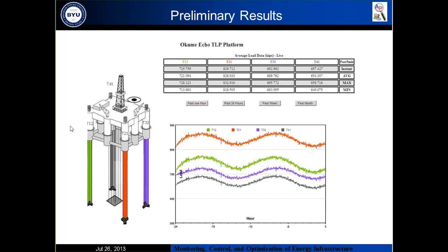We need to calibrate them to a certain baseline, and also because we install these sensors using clamps, the clamp changes the sensitivity of the sensor. So we need to also change the sensitivity. So for calibration, I have two parts: a sensitivity part, and the calibration value itself.